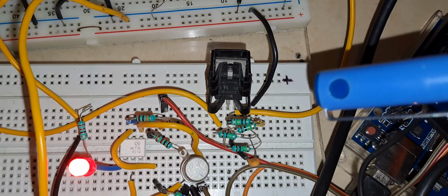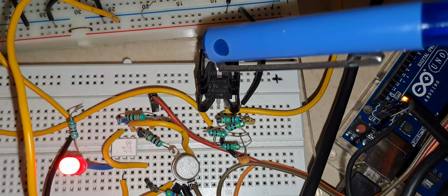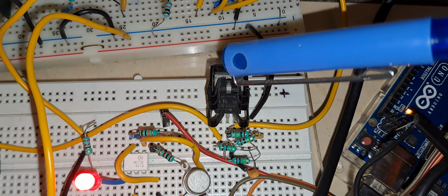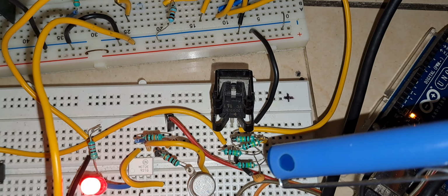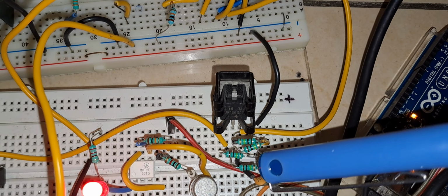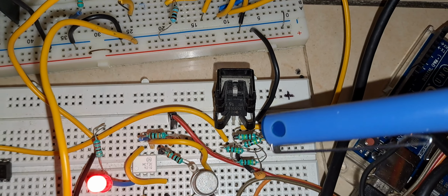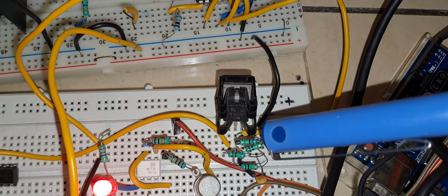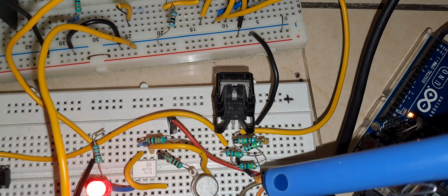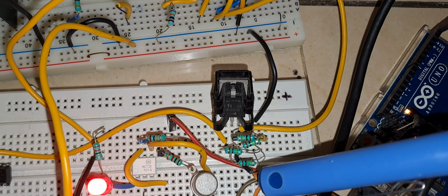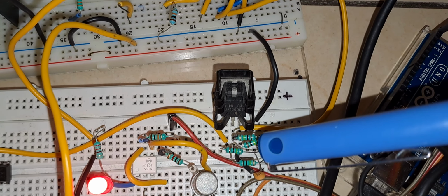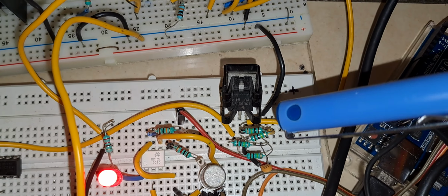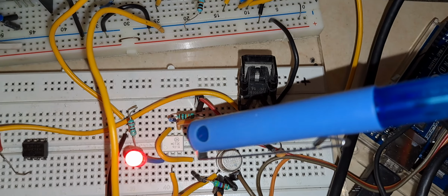I am going to show a clear view of the envelope detector. So this is the Schottky rectifier. You can see this is the Schottky rectifier. I am using 0.1 microfarad capacitor here and 400k resistors. Equivalent parallel 400k resistors is 25k. So this 0.01 microfarad capacitor in parallel to 25k, this is the demodulator. I'll show you the circuit diagram. The output of the demodulator is fed to this